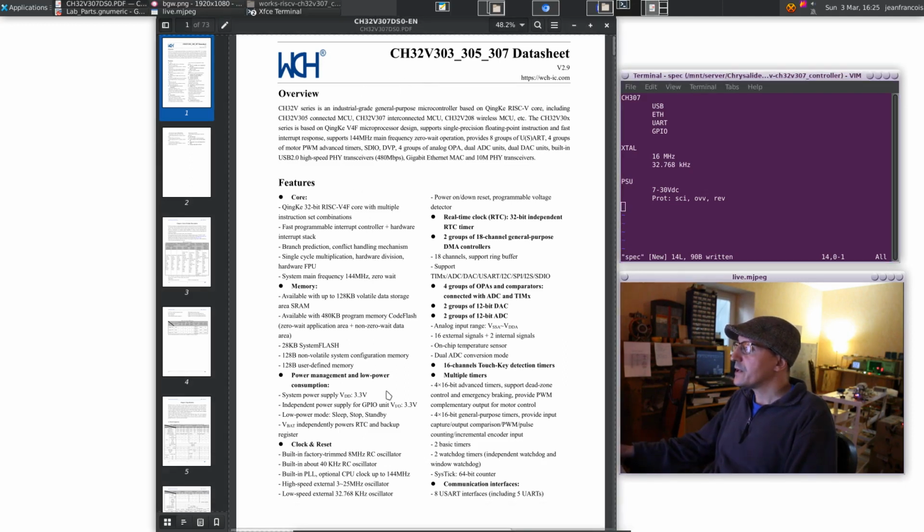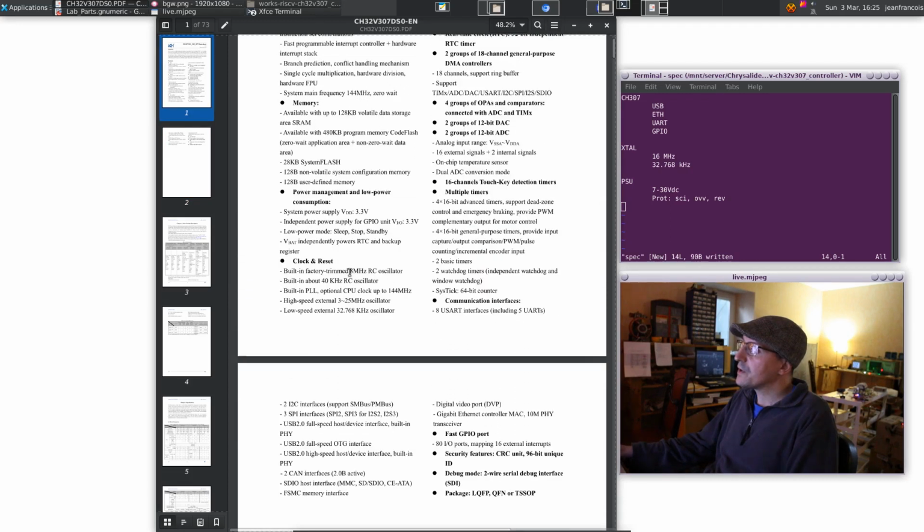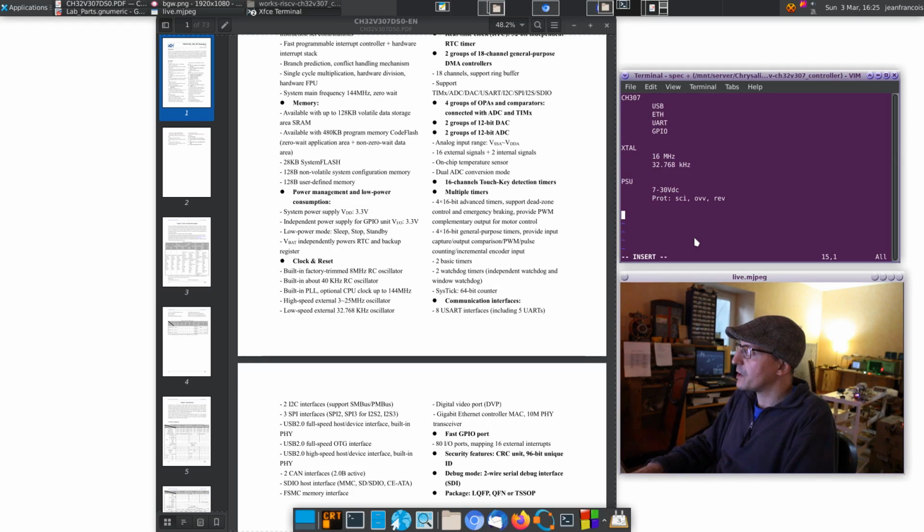So the core datasheet over here. Let's see what we learn more about this core. We have an internal 8 meg RC oscillator. So we talk about the firmware as well. What I want to do is a status LED, because I want to do a backup oscillator. And if we turn into a backup, we want to go into an alarm state, fail-safe. We see that the PLL goes to 144 meg. We leave the options on the crystal selection for future.